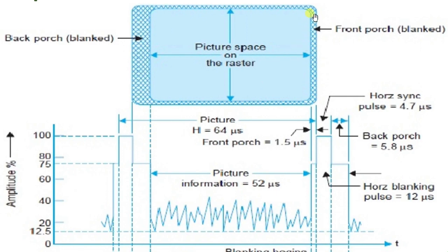After the front porch of blanking, horizontal retrace can begin when the alignment pulse is initiated. The flyback must be blanked because the alignment level is blacker than black. Although retrace generally begins with an alignment pulse, the amount of time required to complete the flyback depends on the scanning sequences. Typical flyback time is 7 microseconds. The blanking time after the front porch is 8.93 microseconds, which is calculated as 10.2 minus 1.27 equals 8.93 microseconds.